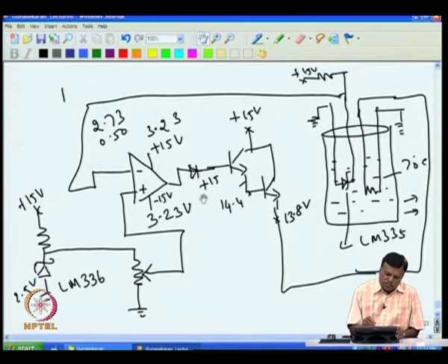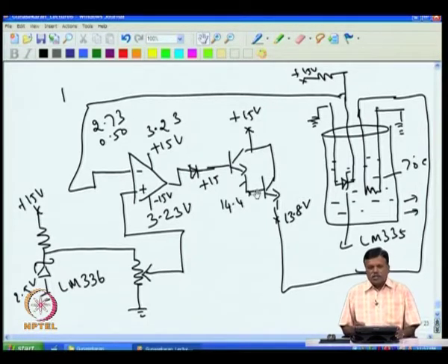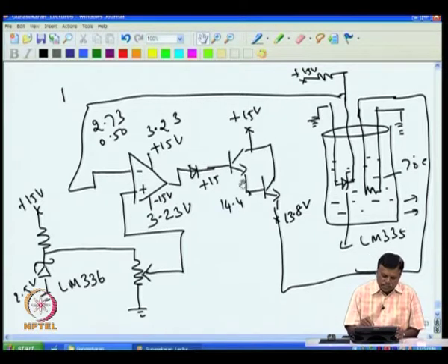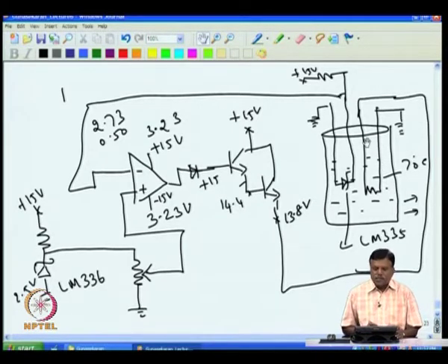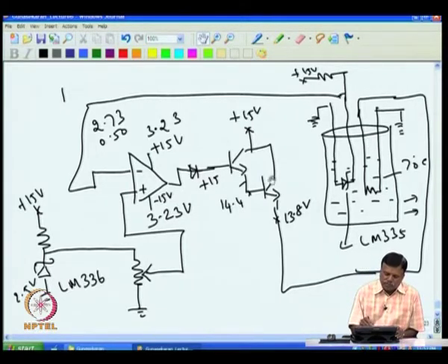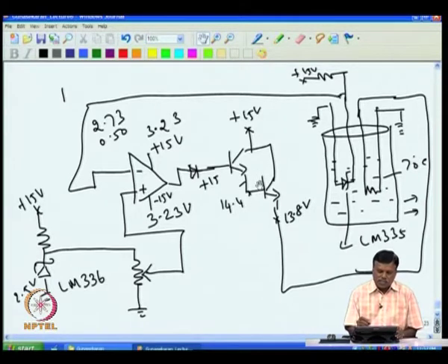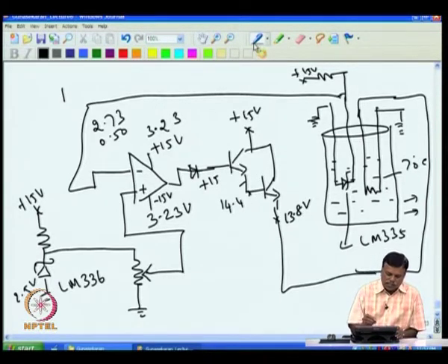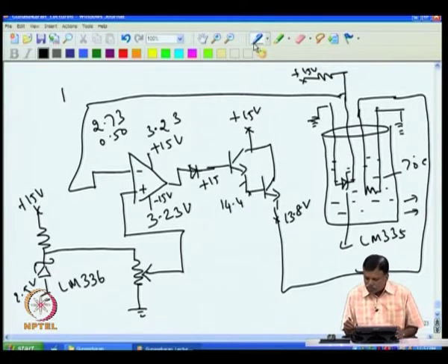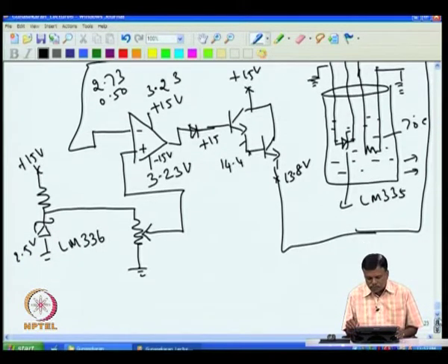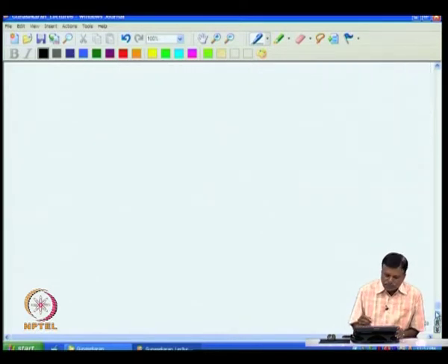And also, in this mode it will be frequently going on and off, and many people even use various other possible drives instead of this, which I will explain a little later. So, in this one, it has an on off feature going very frequently. We can reduce the number of times it goes on and off by introducing a hysteresis. That we can do like this. I will show you in the next circuit.